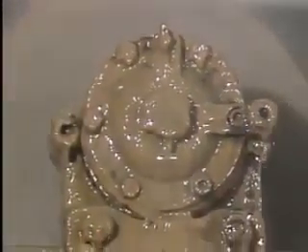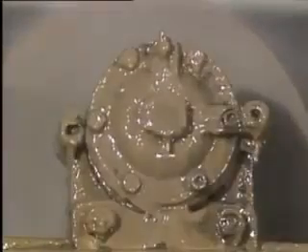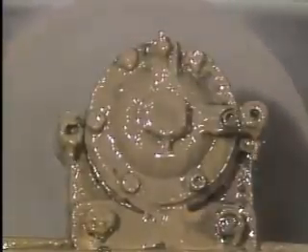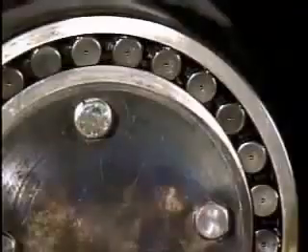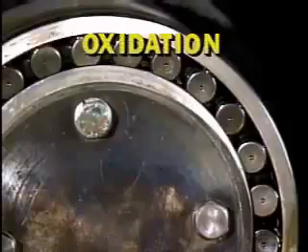Although water and oil or grease normally don't mix well, an additive in the grease used in this bearing makes the water and grease mix thoroughly. This thorough mixing prevents the formation of water pockets that could corrode the bearing. Corrosion can also come from acids produced by lubricant oxidation.